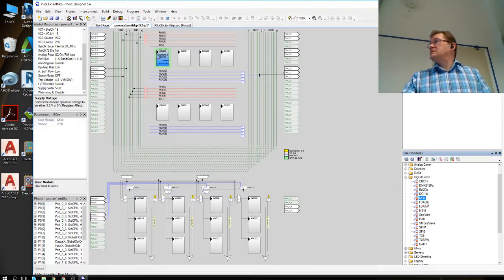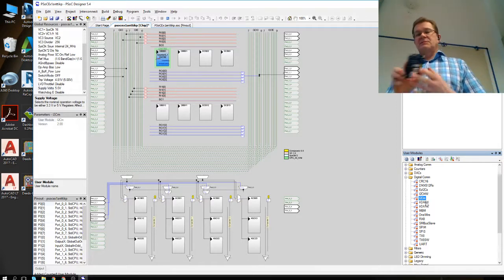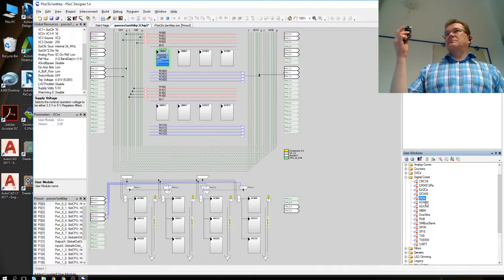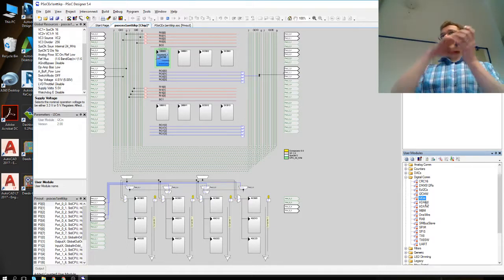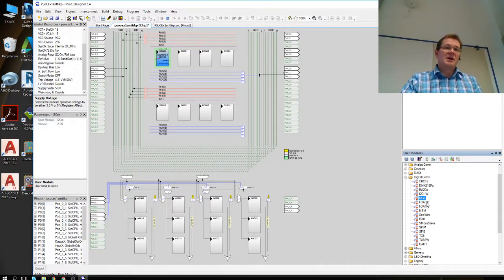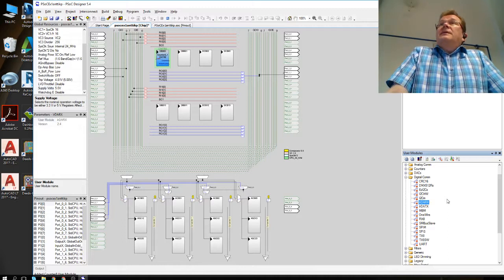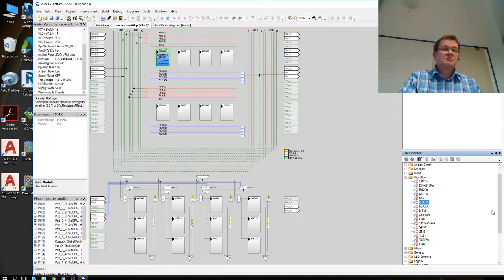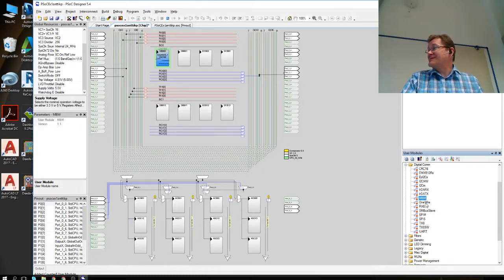One way to use it, basically, if you have a multiple controller system, you have one as an I2C master and the other ones as slaves. So the master would be controlling all of the other processing devices. Okay, infrared data. A standard IRDA, both receiver and transmitter. MBM, I have no idea what that is.